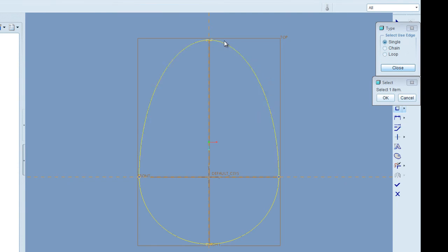We need to have a sketch that's driving the extrusion. So we have to create a sketch from the datum lines that we've done, which are basically the same thing. If we change the datum curves, then the sketch will change as well. But we just need to be careful when doing that, because these two curves need to be coincident at the endpoints.